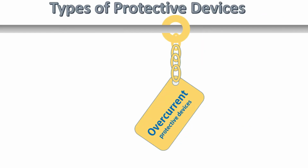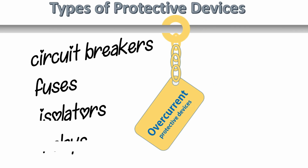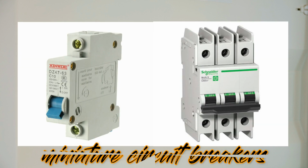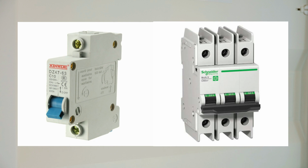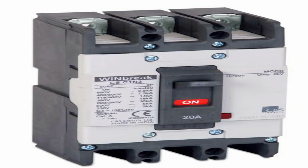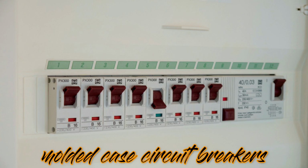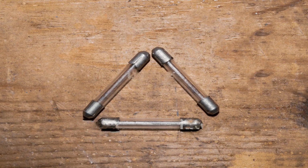The overcurrent protective devices include the circuit breakers, fuses, isolators, and the relays. The circuit breakers in this category include the miniature circuit breakers and the high capacity protection breakers, which we do use for the main feeders, called the molded case circuit breakers.